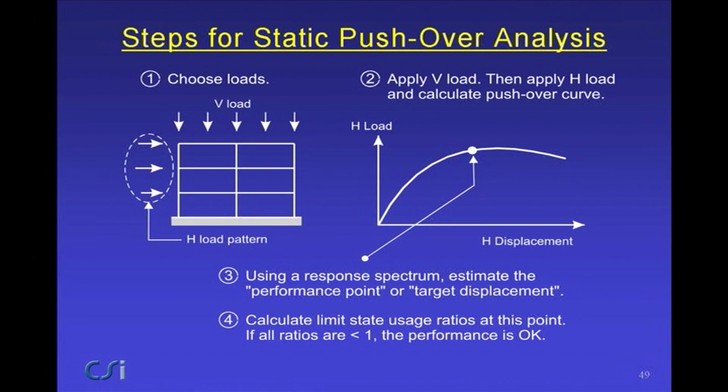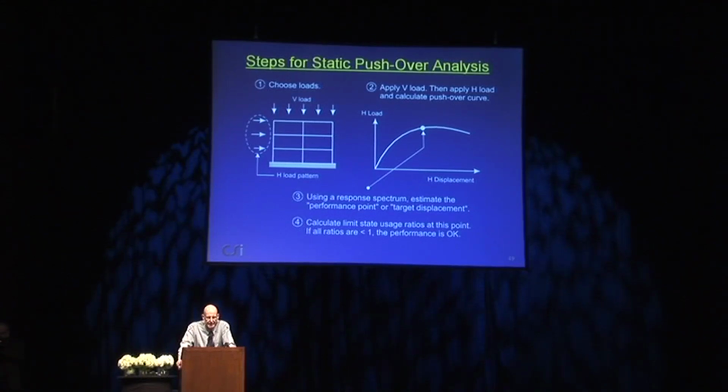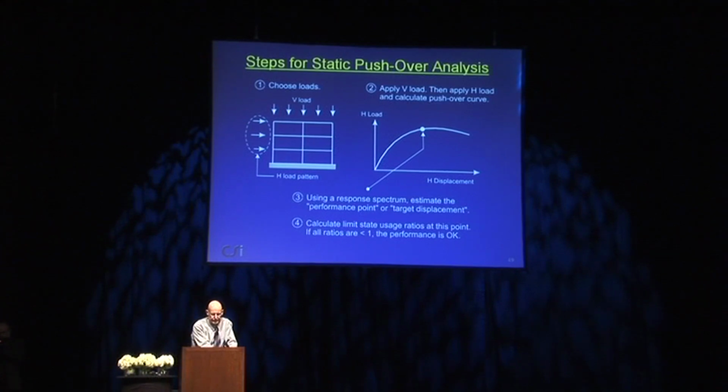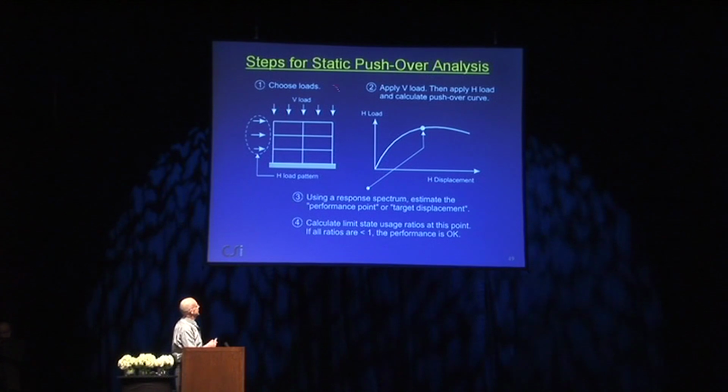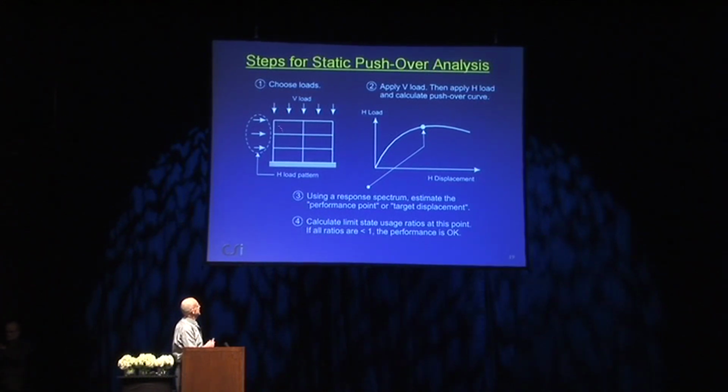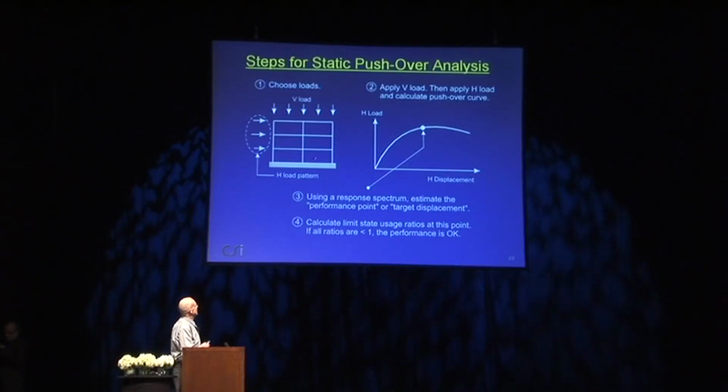reduce the amount of computation, basically. And this slide indicates the steps in pushover analysis. Firstly, you choose the load: you specify the gravity load vertically, and some horizontal load pattern. In this case, it looks almost like a uniform load pattern. It might be linear, or you might base the load pattern on the mode shape, or you typically would have several load patterns and run a number of different pushover analyses, one for each load pattern. But you don't worry about the magnitude at this stage, just the distribution.